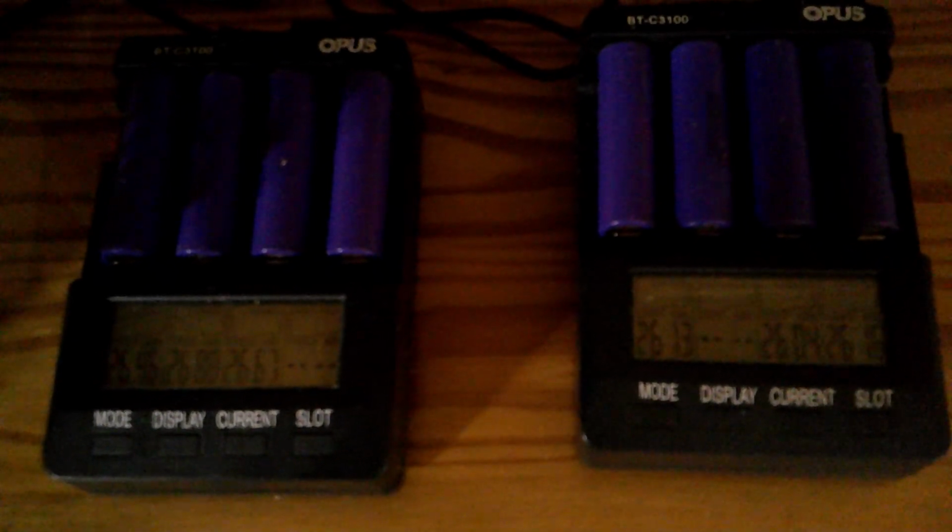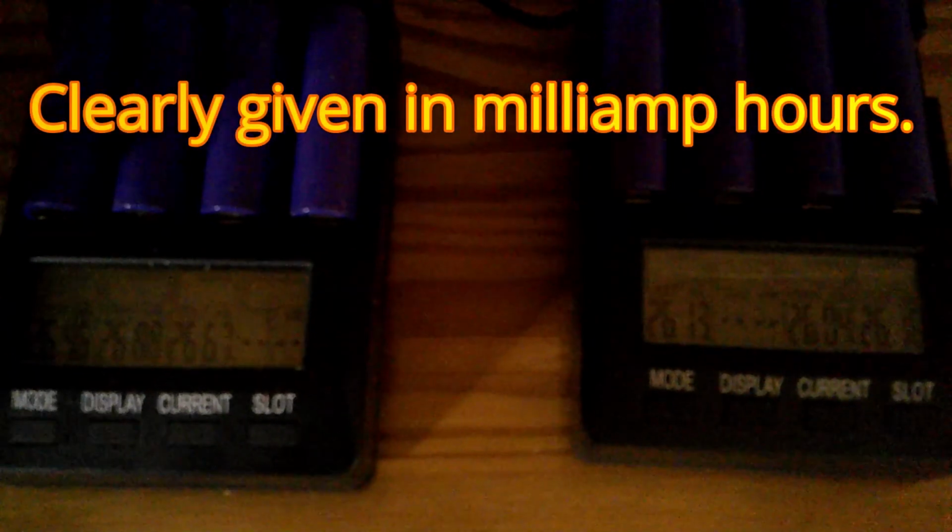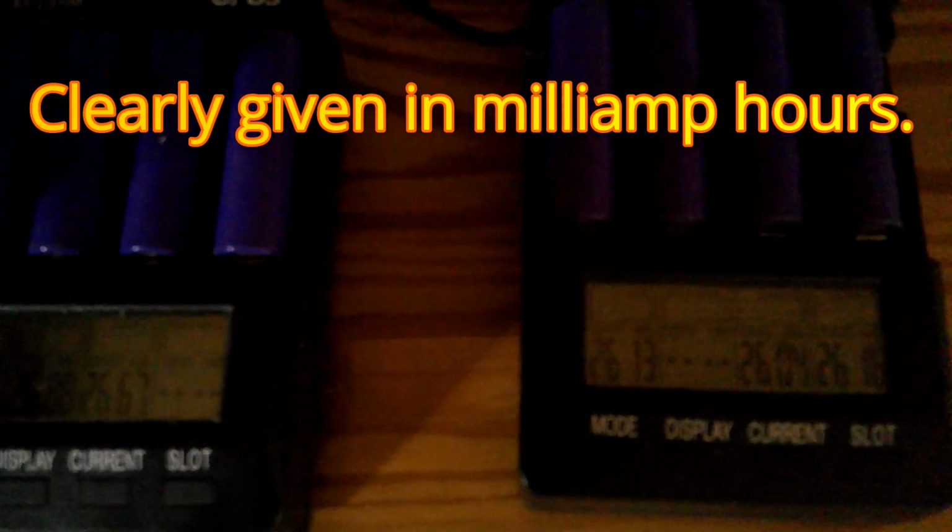Okay, so the battery's capacity has been determined. What it does is it will charge the battery up to the max and then slowly discharge it. I'd use a discharge rate of about 0.2 C, which is about a half an amp. And it'll discharge it down to the low voltage cutoff and measure how much time it takes to do that. And based on that, it can figure out the capacity of the batteries, which is given in amp hours. And then it will charge them back up, although usually I take them off and use another charger to charge them up so I can keep capacity testing the batteries.